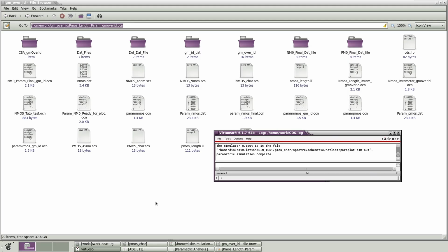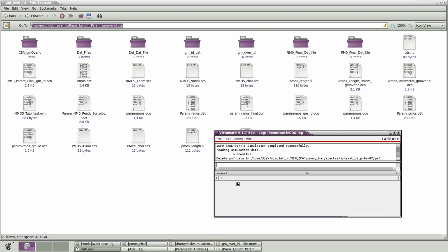Go to your Virtuoso, then use the load function, paste the Ocean file with the appropriate address, and hit enter. It will execute your Ocean scripting into .dat format. You need to be patient and wait at this moment.